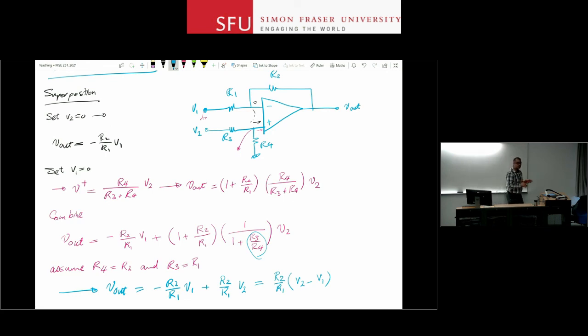And by combining these derivatives and integrated signals, adding them with proper weights to each other and subtracting them from each other, you will have the ability to solve a differential equation in the analog domain in real time. There's no need to wait. There's no need to calculate anything. There's no need to worry about, let's say, convergence or anything like that. You just apply your input signal, let's say it's a sinusoidal, and the circuit solves it for you and puts the corresponding solution at the output. We'll talk about that later on in this lecture.